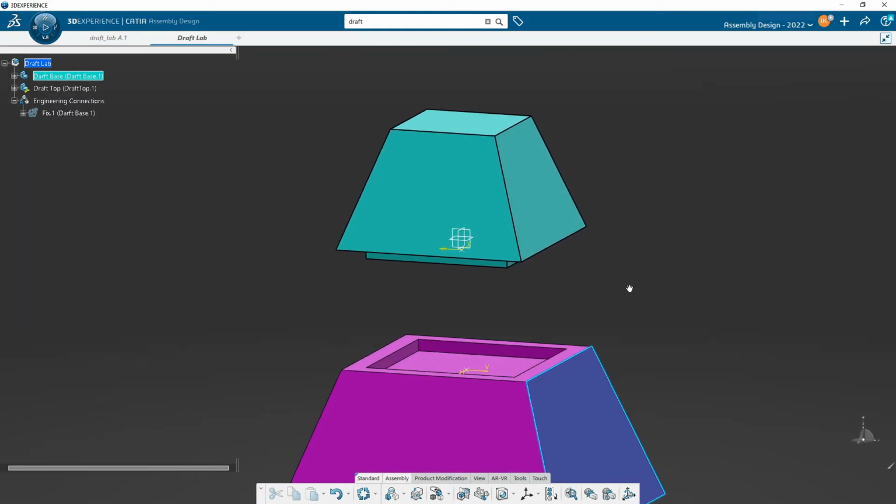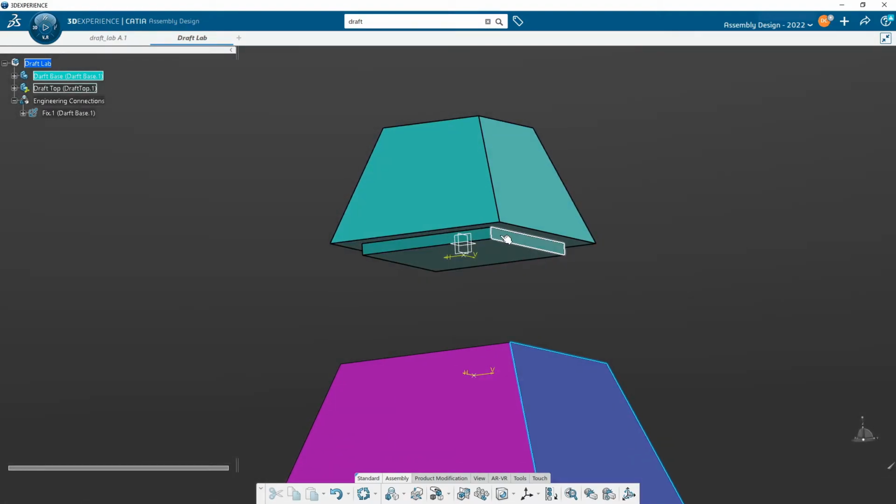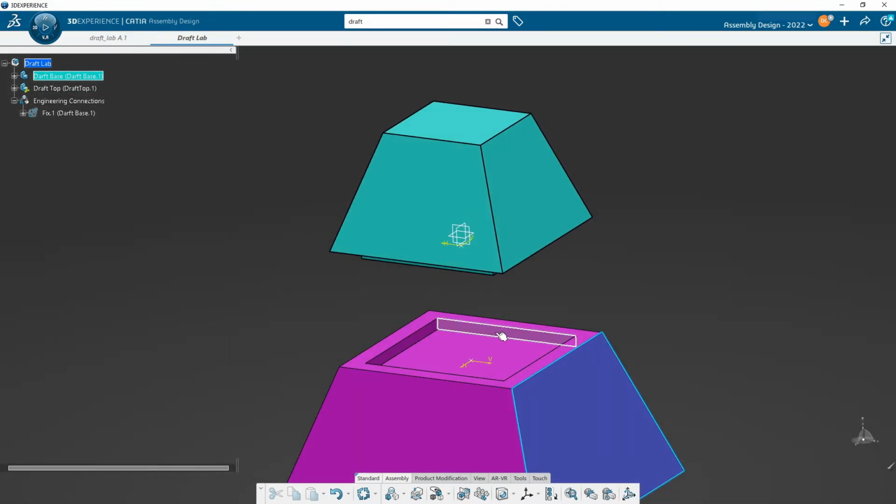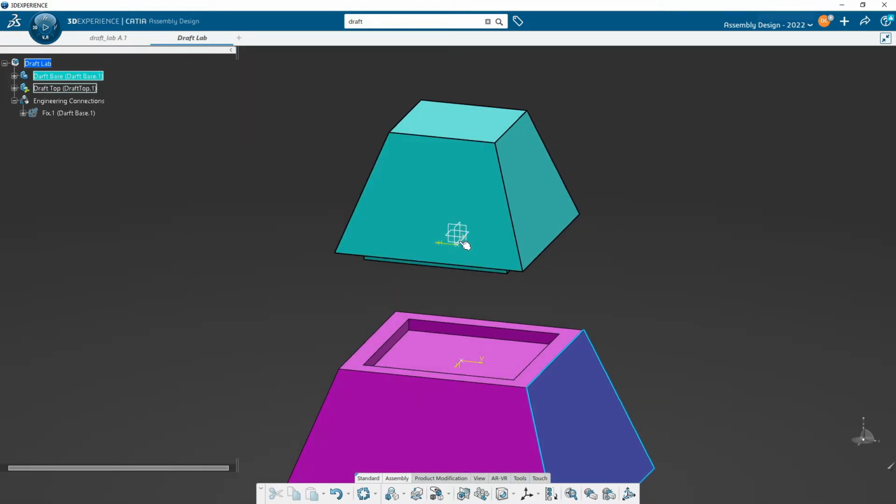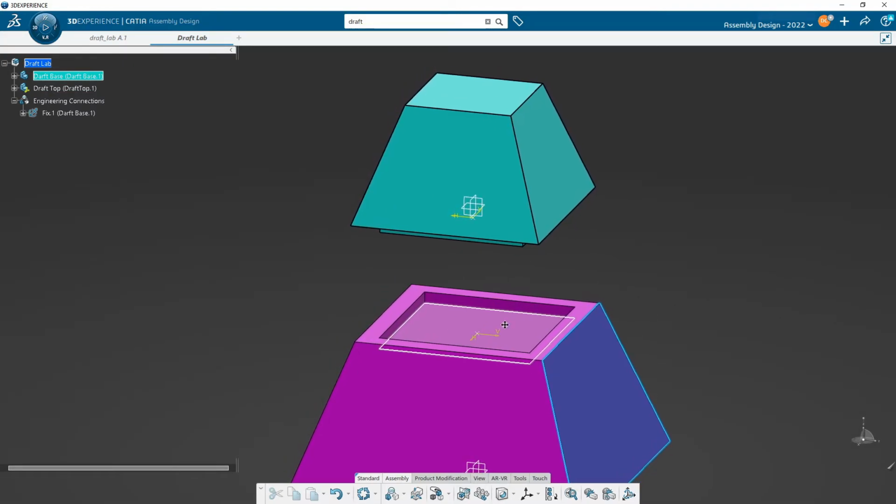But then if I were to change the size of this or this wall right here, that would not change the center point, and so our constraint would still be valid. The issue we'll be left with is if I touch this point to this point, that will suck up some degrees of freedom, but I'll still be able to twist this around, okay?